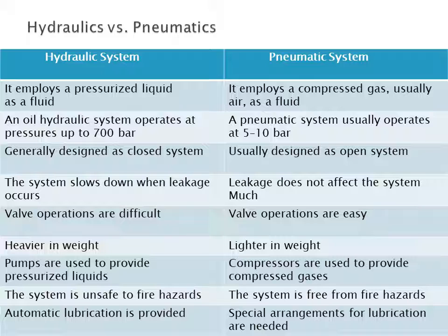The hydraulic system is unsafe due to fire hazard because we are using oil. If there is a failure, or any leakage in the pipes or tank, it may catch fire, right? The pneumatic system is free from fire hazard because it is only air that leaks. You will not find any fire accident in the case of pneumatic system. But in hydraulic system you will have some reports of how the system catches fire.